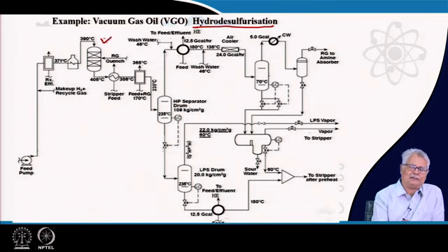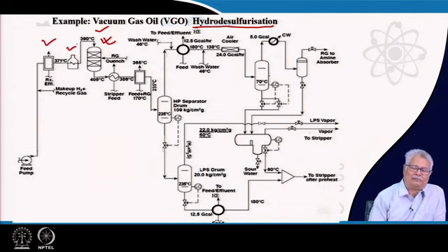Here you have a hydrodesulfurizer reactor. The bottom material comes out, and quite naturally what you have here is it is preheated to a temperature of 390 degrees centigrade. You have preheat exchangers followed by a furnace. You have the makeup and recycled gas hydrogen mixed with the feed. It's a solid catalyzed gas liquid reaction. Now, what you have here is something like this.